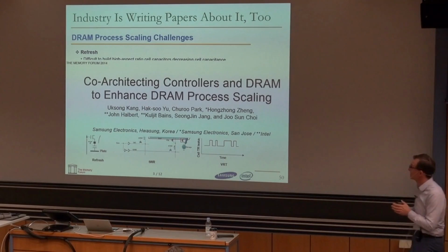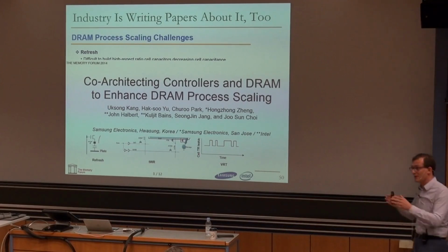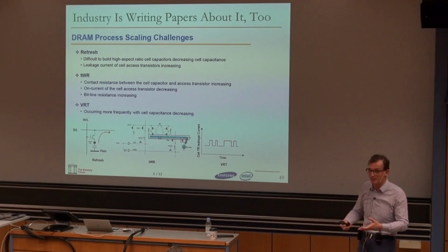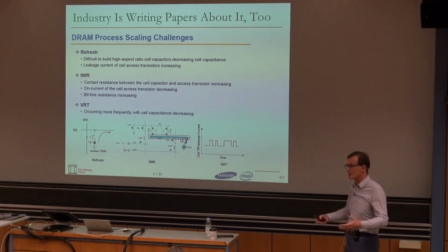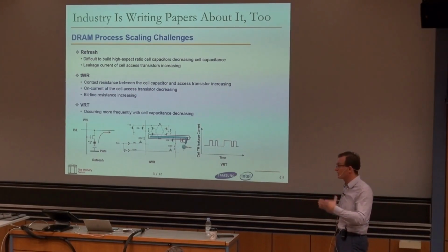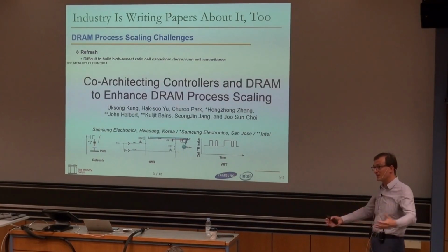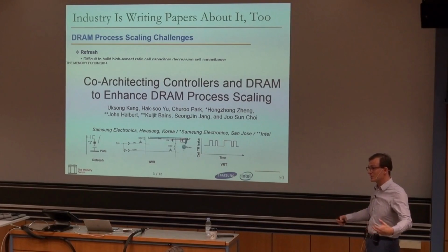So we're at this point right now in memory. And this paper is proposing something that already exists. They propose you should have error correcting codes inside memory because it's very difficult to tackle these reliability problems at the circuit level or the device level. So you'd better correct the errors when they happen with error correcting codes. These error correcting codes occupy area inside the memory. You cannot use it. Basically, it's lost capacity.